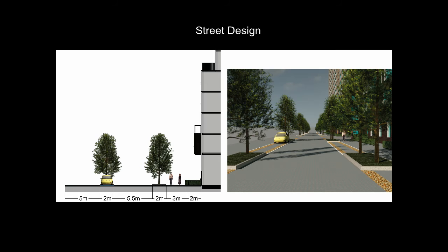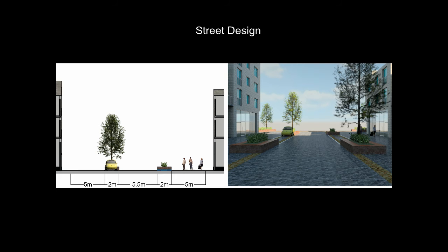The design of the road is based on the guidance provided in Manual for Streets. The central lane is 5.5 meters wide, which allows for 2 cars. There is 2 meters semi-private space marked by the hedge to allow for privacy and mark private territory. The side lanes are at least 3 meters wide to make it easy for people to walk. Despite the markings, there is no change in road levels. The use of same road material, both for pedestrians and vehicles, mark it as a shared surface.